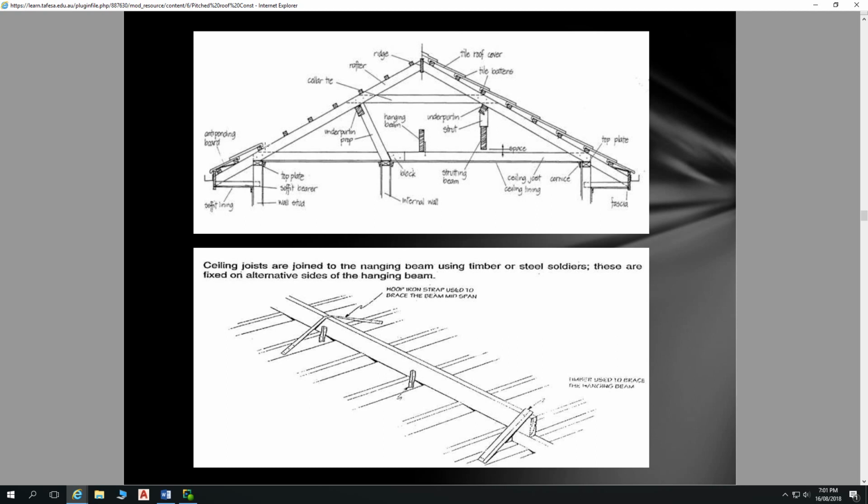So that's our boxed eave. That's done for structural reasons, and also it's a very simple detail to build as well. But once again, the aesthetic of that is a bit more colonial, a bit more traditional than a raked eave, for example.